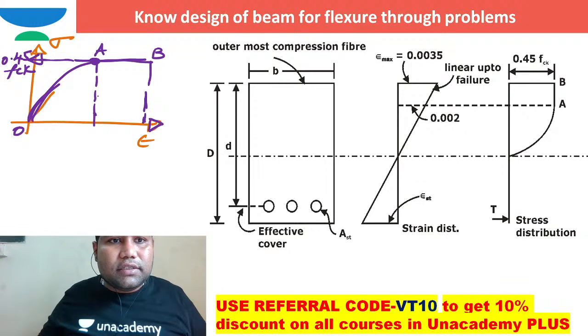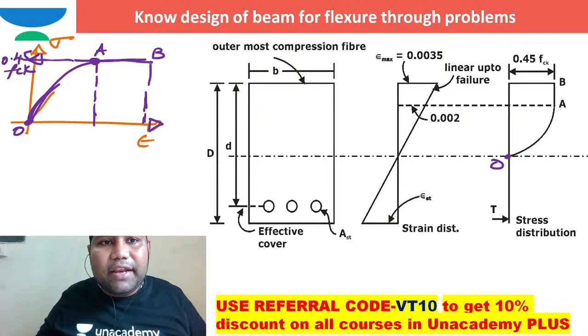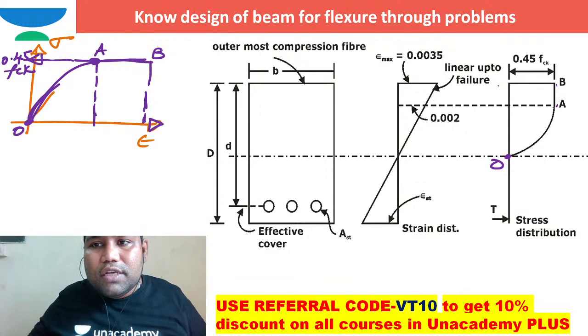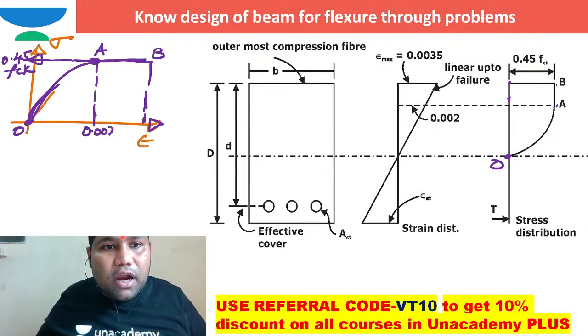Now this is point O, this is point A, and this is point B. At point A, you tell me what is the strain. AB is nothing but the crack widening zone. From A to B, the variation of stress is just like a rectangular variation, right? And the strain here is 0.002.